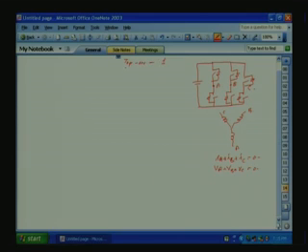If the bottom switch is on, we will mark it as 0. So, for each pole there are 2 states possible, either 1 or 0. There are 3 poles, so you will have 2 raised to 3 states, 8.